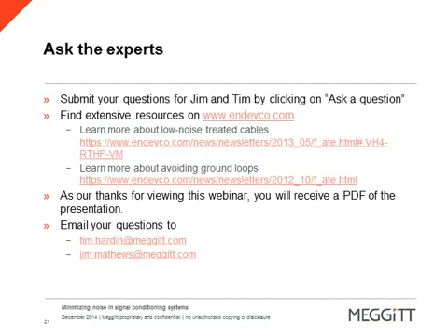Yeah, and also, Tim, if I might add, there are so many variations of non-conducting medium out there. There's tapes, there's epoxies. I know we're talking about noise here, but you also have to look at your bandwidth. Every time you put something in between the accelerometer and your mount, you're going to damp the high frequency. It's the old "it depends" thing. How high a frequency does that matter? Are you mechanically going to dampen it with an isolated stud or some epoxy? If it's at lower frequencies, then it's not as much of a concern, but you might want to keep that in mind.